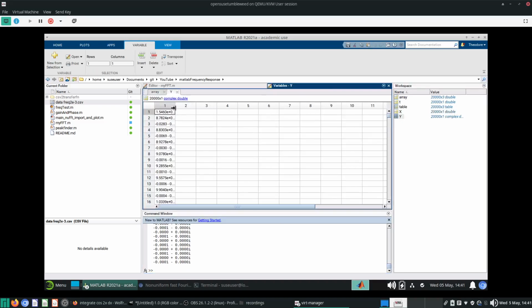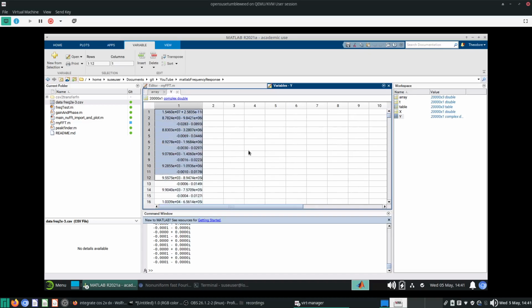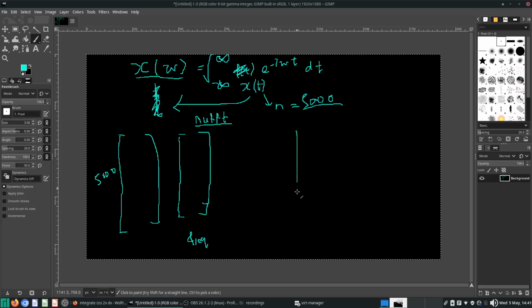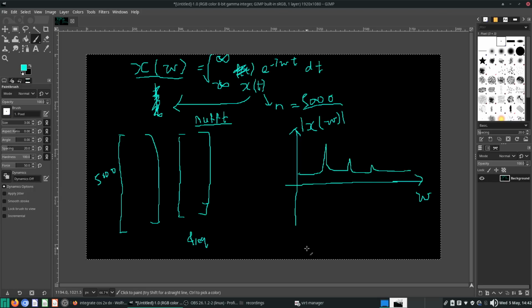Okay, so the new FFT runs very quickly, and you'll see there's a complex number. Again, the phase data is captured by the ratio of the real to the imaginary part. The magnitude data you can just use to plot, and you will get the spectrum plot. So if you have magnitude of X of omega, this is the common plot that we like to see. We have peaks of data which you will see over here. This is the end result we often want to get.